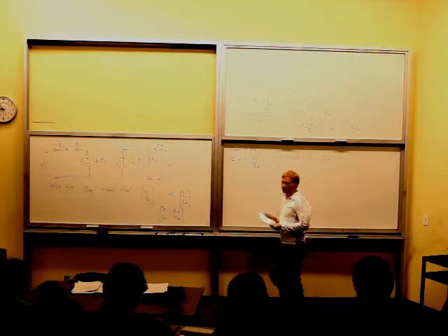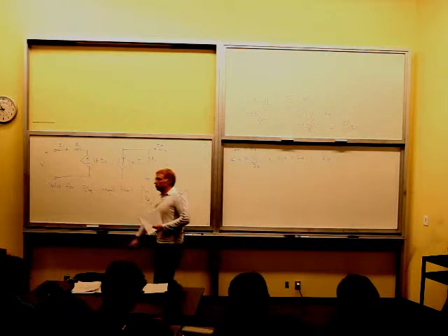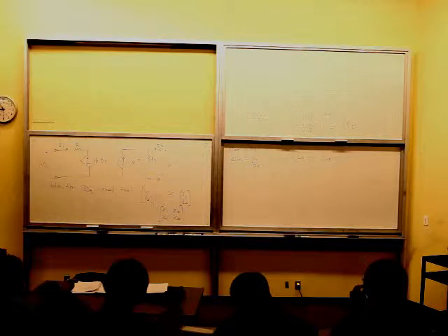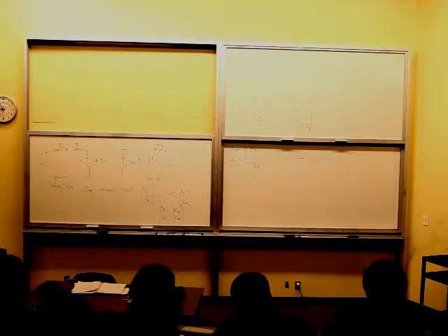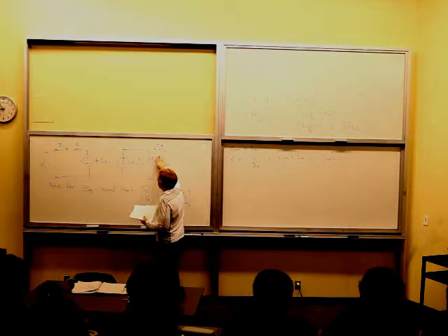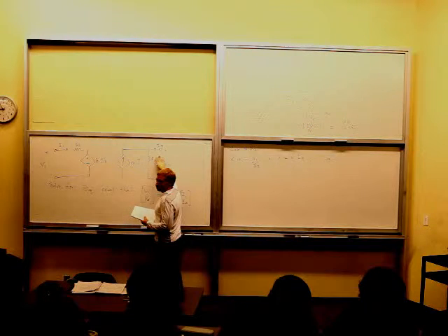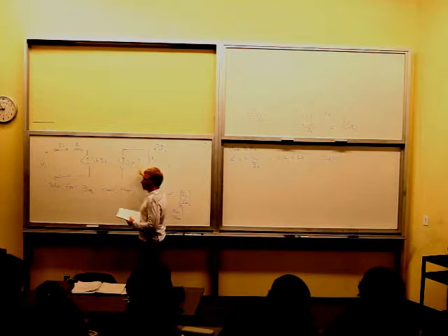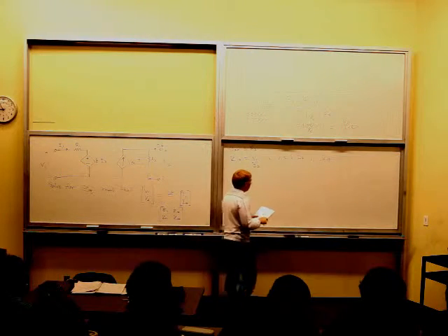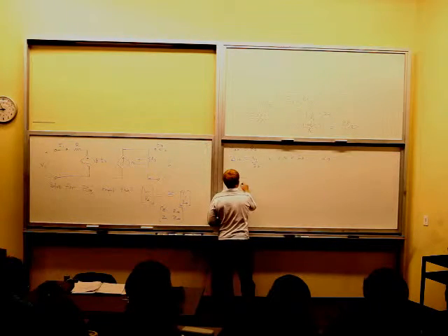So there we go. We just found the four parameters. Yeah, Z21 is A? Yes, that's the matter. Why would you think it'd be 0? Because if you open circuit this second right-hand side, both your dependent sources go to 0. Not all my dependent sources go to 0. This dependent source is dependent on I1. Yeah. No problem. Okay, so I've got my Z matrix.